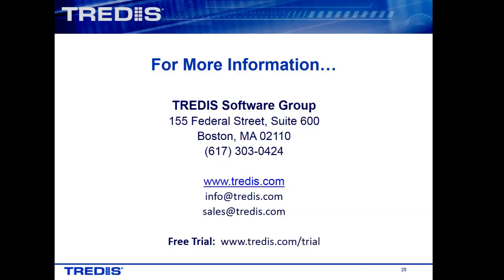Thank you, Adam. Another question. Are default travel costs available in the model for the region selected? The TREDIS default mode purposes have vehicle operating costs and fuel consumption rates that are associated with national averages, but you have the ability to modify any of the default modes to have more regionally specific costs if you have information on your specific MPO region or state.